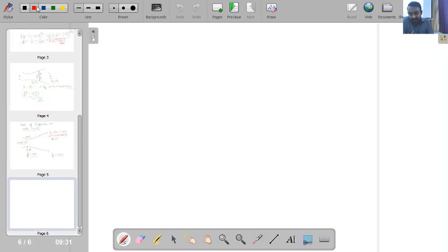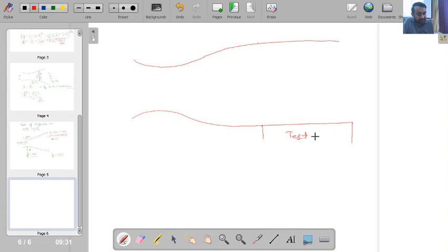Now, to see what other possibilities we have, I will consider a diffuser section like this. What I have done is not a direct exit; where the nozzle ends, from this point I have taken a horizontal constant cross section duct, and this duct is nothing but my test section. Now in this duct I want my Mach number to be 3. This is the exit of the nozzle, given by point E.